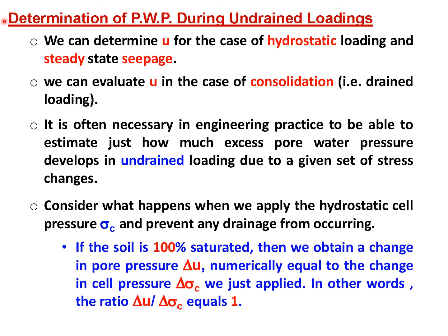Determination of pore water pressure during undrained loading. We can determine pore water pressure U for the case of hydrostatic loading and steady-state seepage. We can evaluate U in the case of consolidation, that is drained loading. It is often necessary in engineering practice to be able to estimate just how much excess pore water pressure develops in undrained loading due to a given set of stress changes.